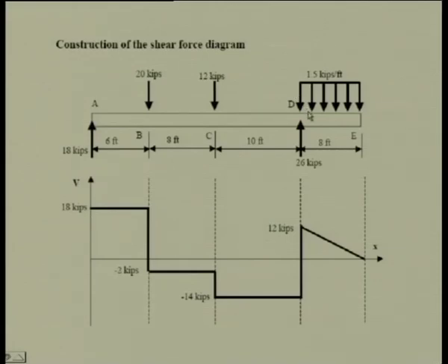It is a load, remember these are all loads. What we call the shear force is a sigma load. This itself is a load, the load acting at 1.5 kips per feet at this point. So, as you can see, when you keep adding the negative values to this 12, it will keep going down till the end, where it reduces to 0. So, there is no force there.